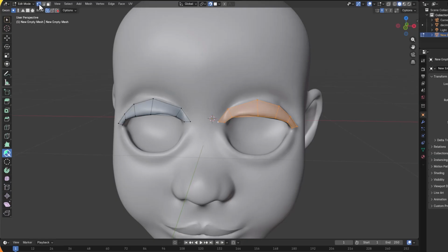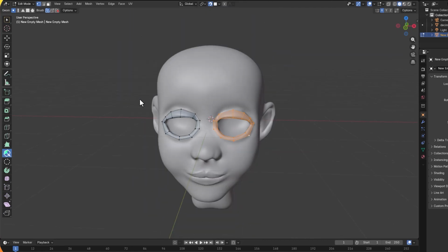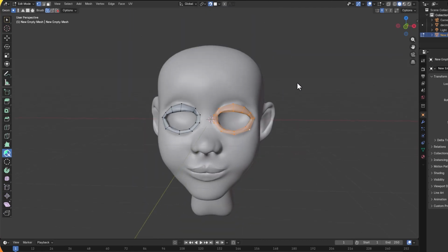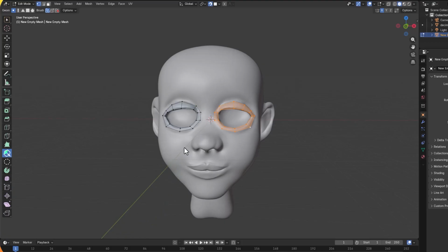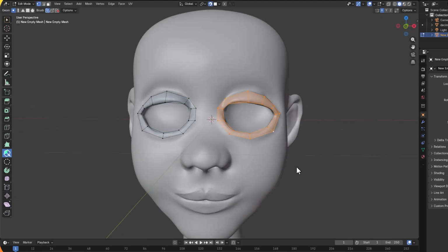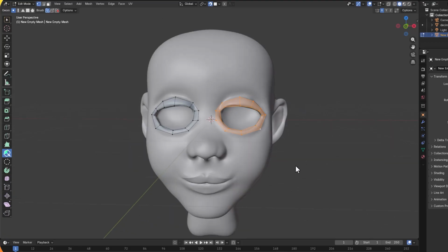So I'll go back again there and I'll try to get 1 face, 2 faces, 3 faces, 4 faces, and 5 faces. So I press Shift again and fill, that's kept there. You see how we create this. That's the loops for the eyes. We already created this. We need to create the loops around the nose.